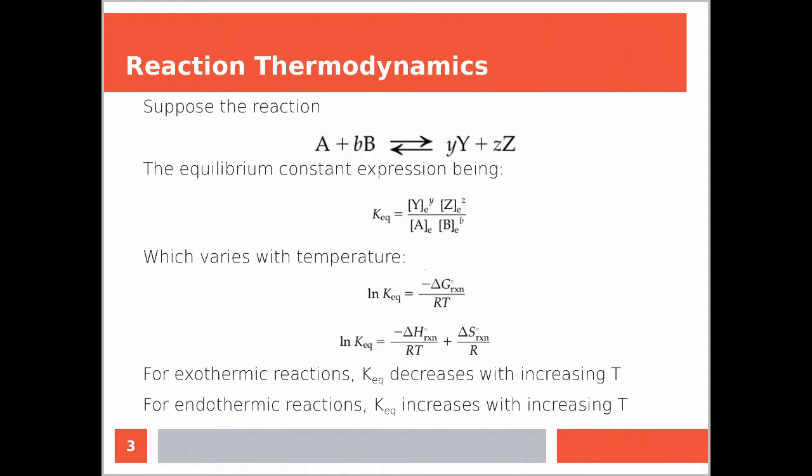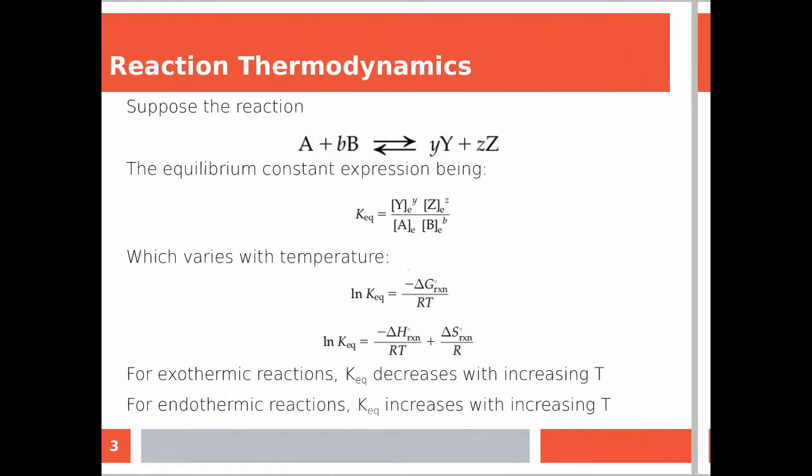If you have exothermic reactions, of course over time your system will have increasing temperature. Sometimes, if you do not have a proper cooling system, the heat will accumulate in your system. It will increase the temperature, and you will get lower and lower yield as the reaction proceeds. Those are the things to consider in designing reactions. This is one of the importance of knowing reaction thermodynamics as it applies to designing bioreactors.